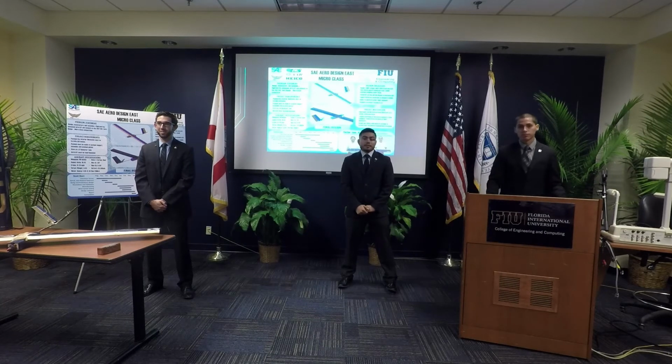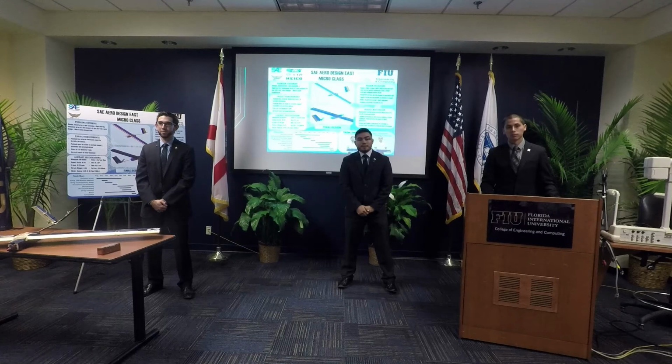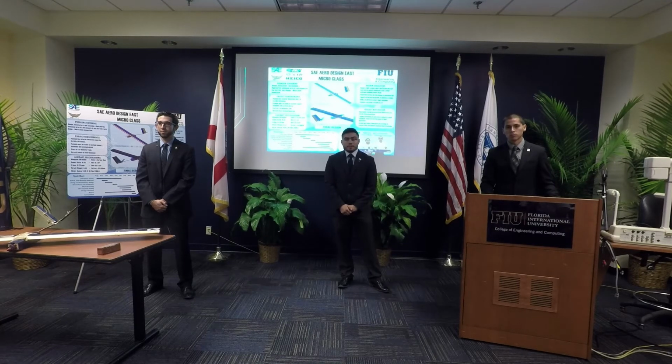So you flew it without the camera though? No, we didn't fly without the camera. We are planning on doing that later today though. But when the camera was placed in front of the aircraft, right behind the motor, it shifted the CG forward. So I did notice I had to give a lot of up elevator to keep the nose up. So I do expect it to fly level without the GoPro in front of the CG.